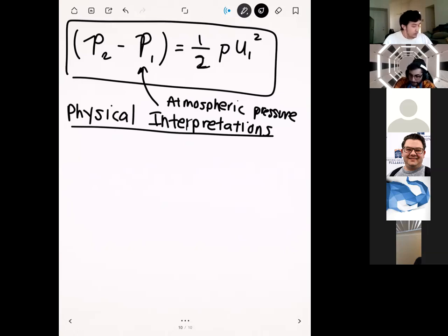Okay. So far, when we derived the Bernoulli equation, we derived it in terms of Newton's law. So we used force is equal to ma, basically, right? And that's one way that you can interpret the Bernoulli equation, is that Bernoulli represents all the different forces that can drive a flow. So we have the pressure term, and then we have the gravity term, and then that results in some velocity. But remember that velocity came from our acceleration. Okay? And so that interpretation is fine. That's the Newton's laws interpretation of Bernoulli.